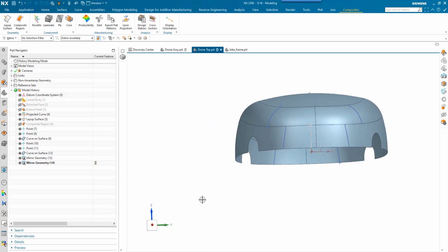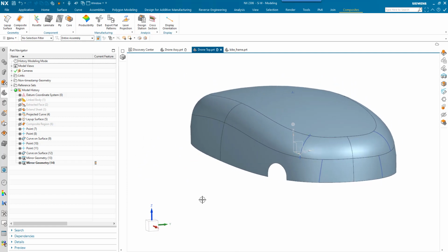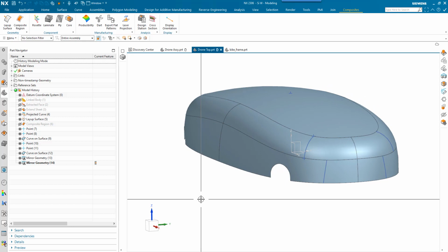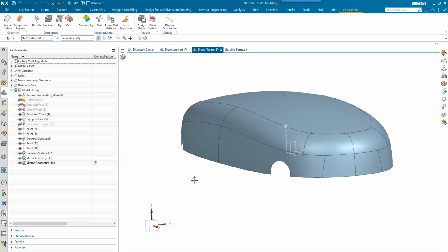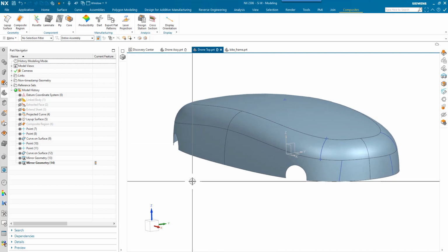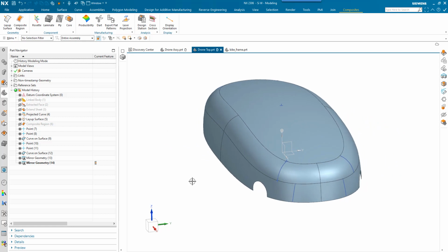So this zero thickness surface is used to help define the carbon fibre plies and the laminate. It's extended a couple of mil because it'll always be trimmed back when it comes out of the mould, or if it's going to be joined together it'll need an overlap so the two halves can be bonded together as well, or joined together.